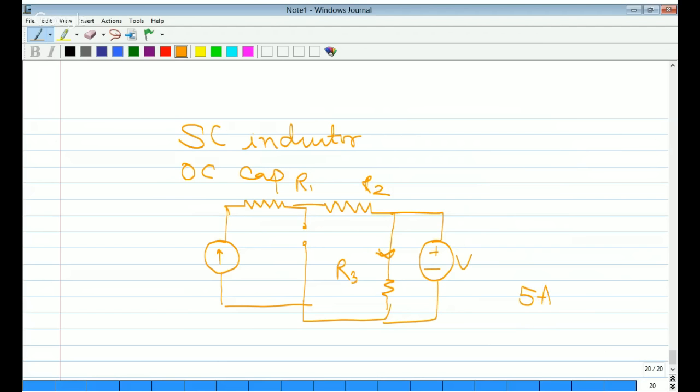Next, what it has asked? And the voltage source current through the voltage source. So here it is 5 ampere. Here I source is 1 ampere. 1 ampere is current coming here. So this will supply 4 ampere. So answer will be D, that is 5 and 4. Okay.